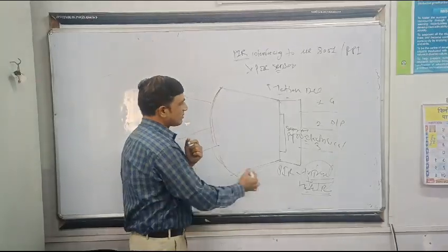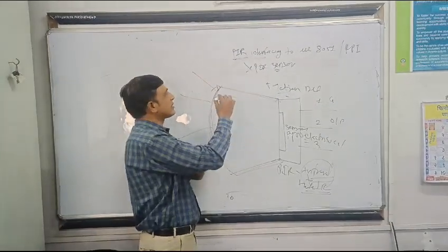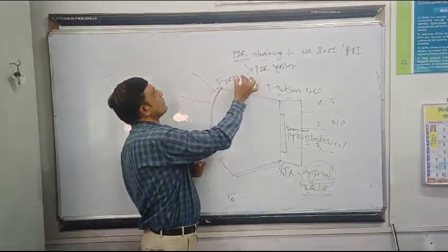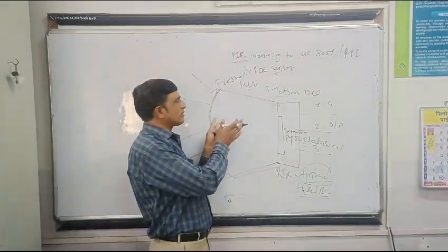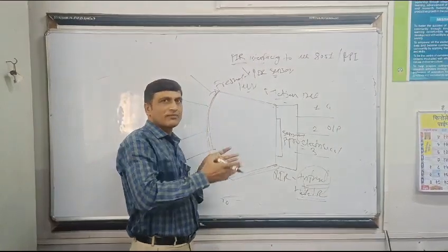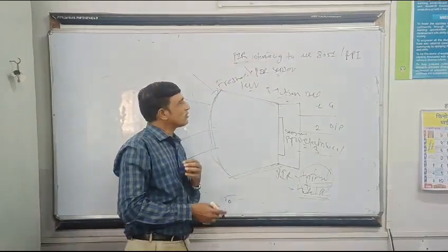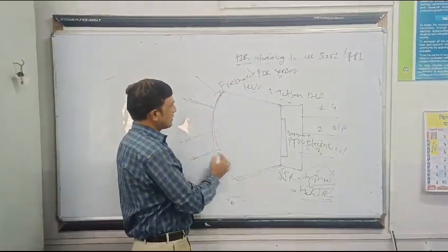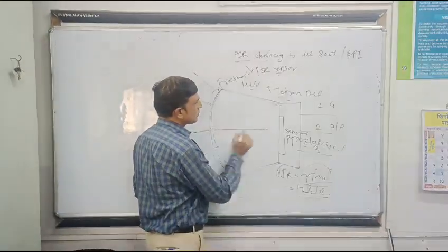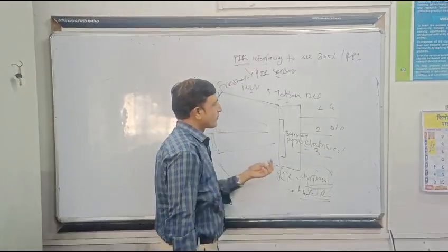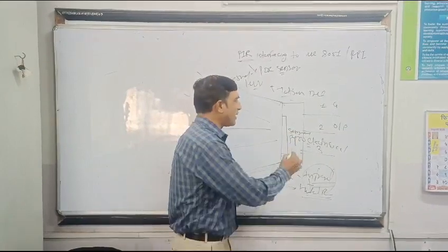Now how is the sensor going to sense the heat signal? If you see the structure of the sensor, it comes with a dome, or you can say a lens. This lens is called a Fresnel lens. What is the purpose of the Fresnel lens? Its purpose is to capture the heat signals radiated from the heated body. This lens captures the heat signal and focuses it onto the center point of the PIR sensor, where there is a pyroelectric material.